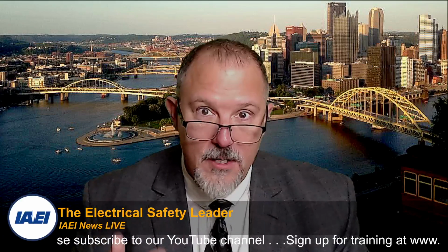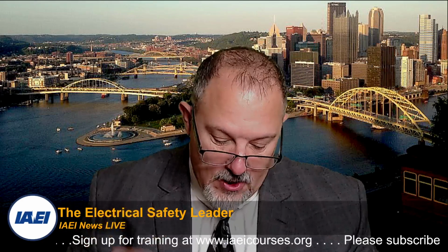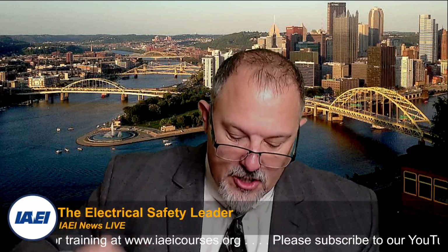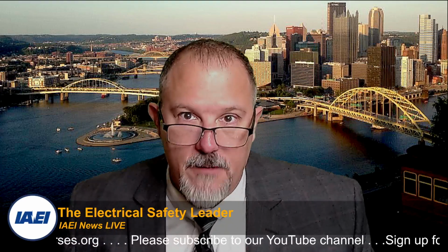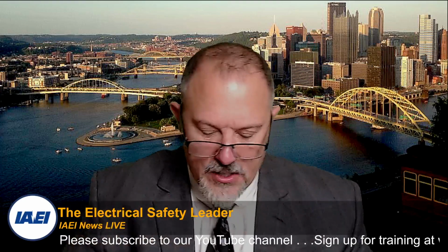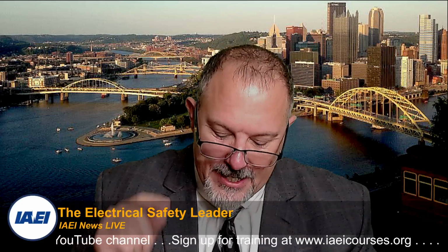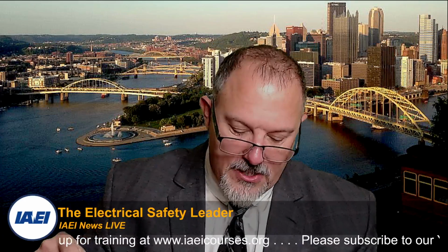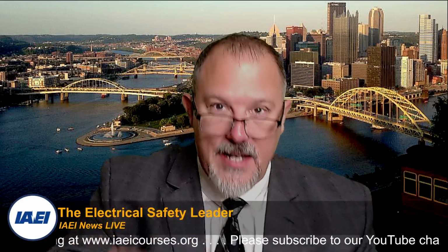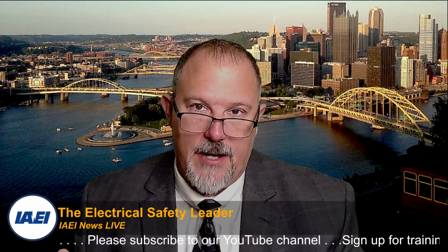Now, the third little subdivision, it says inverse time. All right, so inverse time. Oh, I need these. A qualifying term indicating that a circuit breaker does not have any adjustment to alter the value of the current at which it will trip or the time required for its operation. So, I'm sorry, inverse time. I read the wrong one. A qualifying term indicating that there's a purposely introduced delay in the tripping action of a circuit breaker, which delay decreases as the magnitude of current increases. Inverse time is the higher the current, the faster the clearing time.